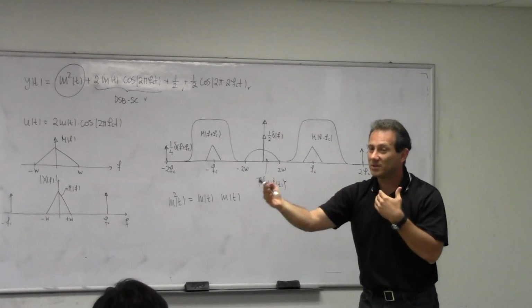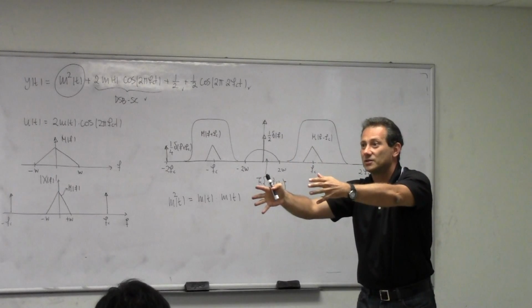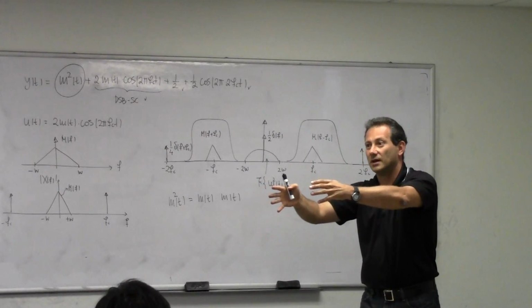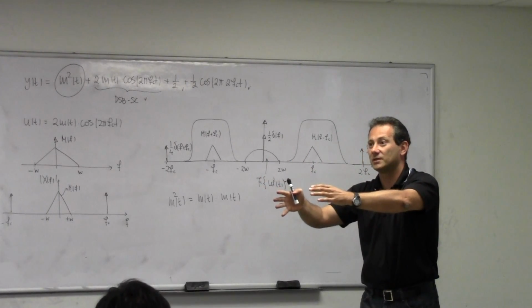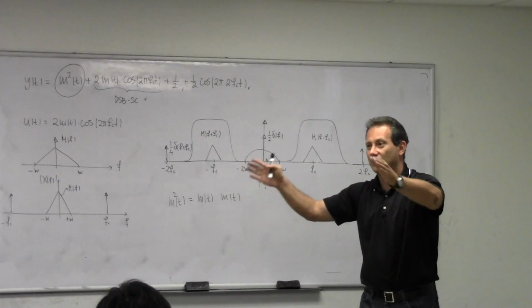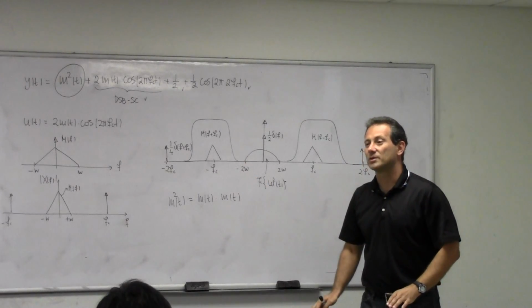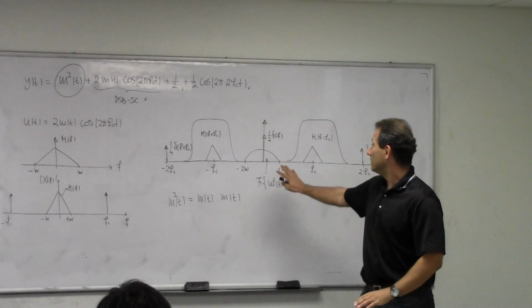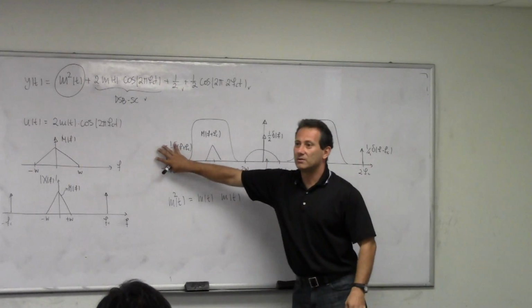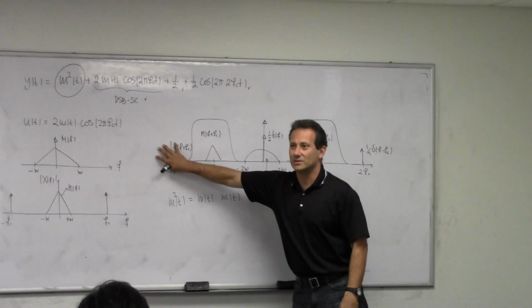If you look at the transmitter side of all the communication equipment, the last stage is a bandpass filter that rejects out-of-band emission, right? That filter lets your signal go through and then rejects everything that you're not supposed to be transmitting. Because otherwise, if I transmit here, I'm going to be stepping on somebody else who's authorized to work in this range, right?